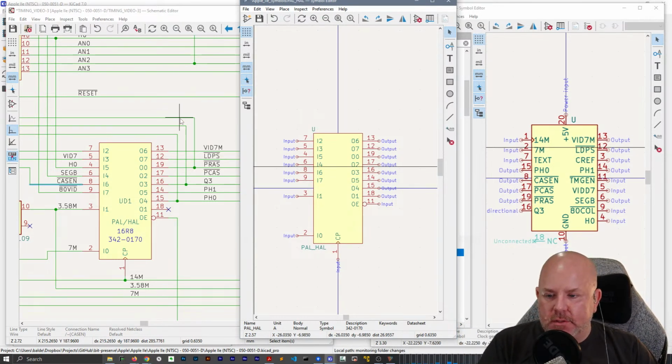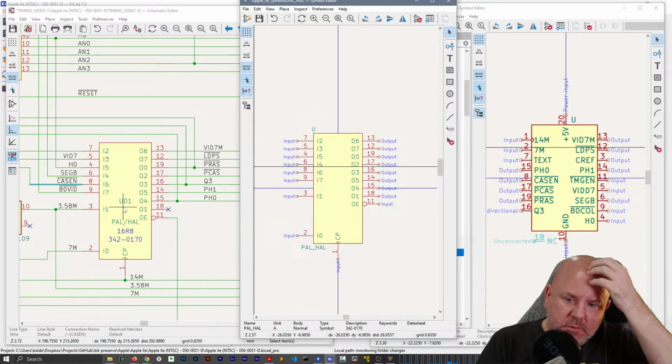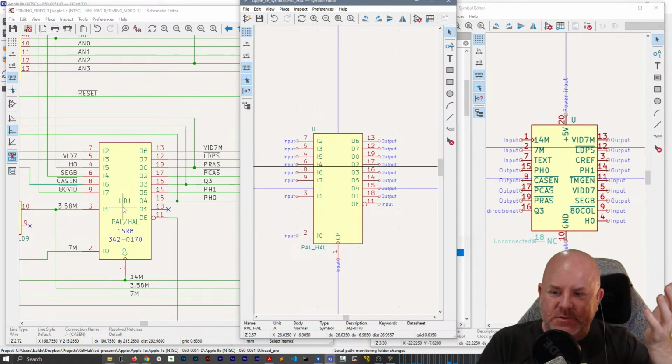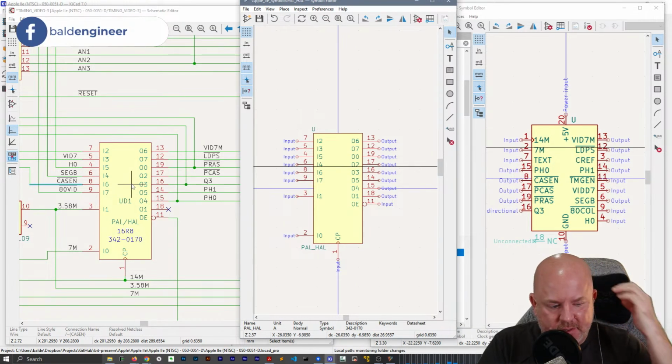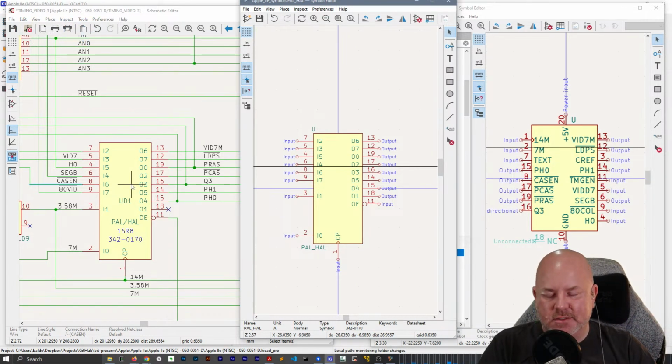Oh, these are not PALs. Okay. Yeah, this is actually not a programmable array. First, it wouldn't really be interesting because these are basically just all shift registers to divide. It's just a clock divider, and so I think this was an uncommitted logic, but it's not programmable. They're all masked.